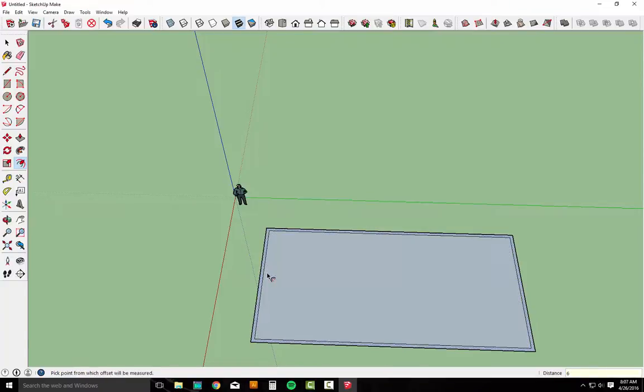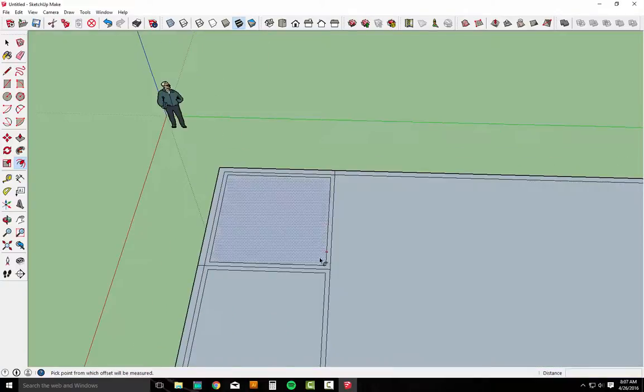From there, I'm going to start drawing all of my interior walls. So if I've got an interior wall over here with a bedroom being 10 foot by 10 foot, come in 10 feet, 10 feet, gets me exactly a 10 foot by 10 foot bedroom. Same thing over here. Offset these walls 4 inches for our interior wall thickness. And we've got our interior walls.